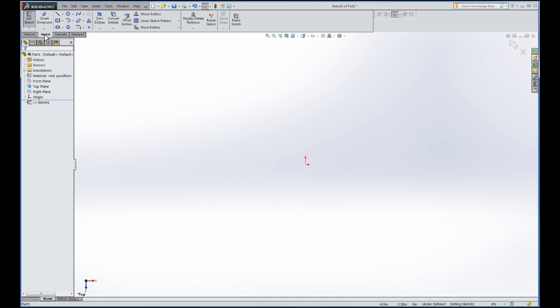So in the Sketch tab, our main controls are this set right here. This is how we'll be sketching entities, they call them. And a rectangle is a nice one to start with. There are different types of rectangles, different ways to control a rectangle. I'm going to click the little down arrow next to that square, and you can see you can define a rectangle based on corners, a bottom left corner and an upper right corner.